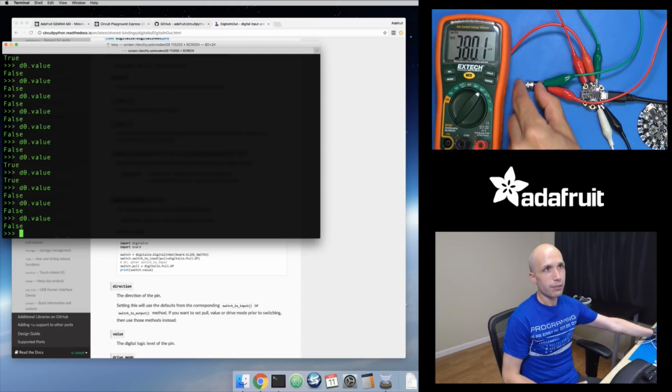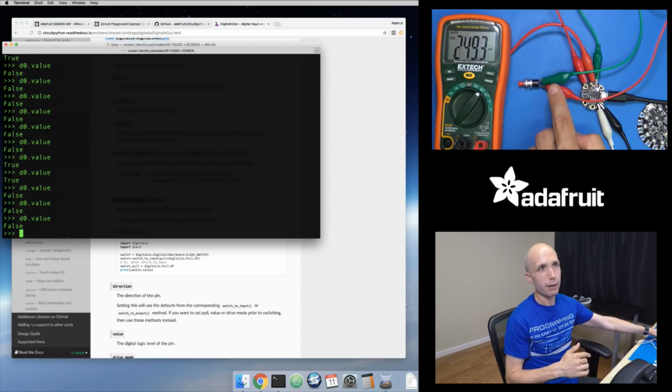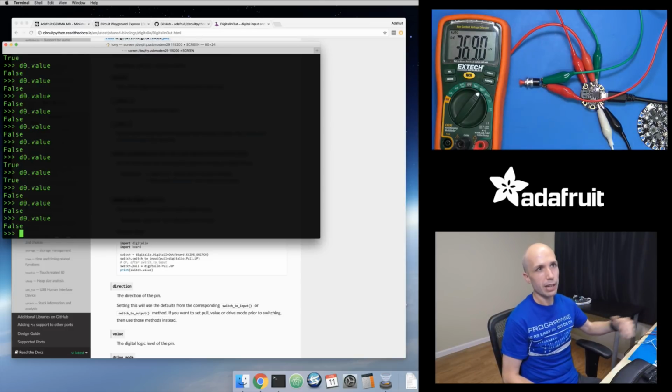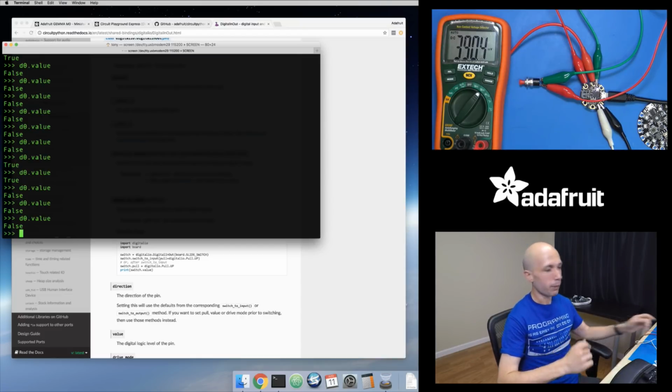And then when I press the switch, it's going to connect it to 3.3 volts, and I'll read a high logic level. So, because I have a high logic level as my input to one side of the switch, I'm going to put a pull down resistor. I could swap this though. I could have ground connected to the other side, and then in that case I'm going to want a pull up resistor so that it naturally stays at a high logic level, and then when I press the button it connects it to ground and I'll read a low logic level.